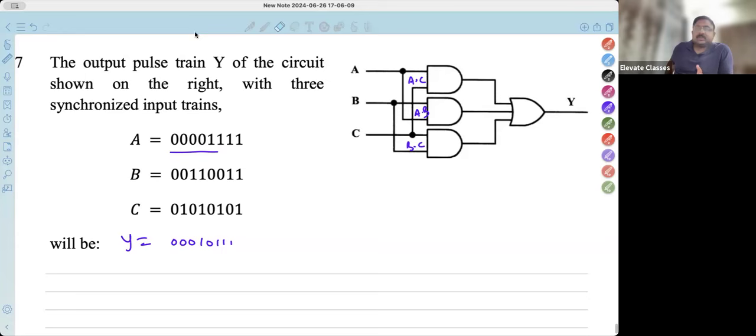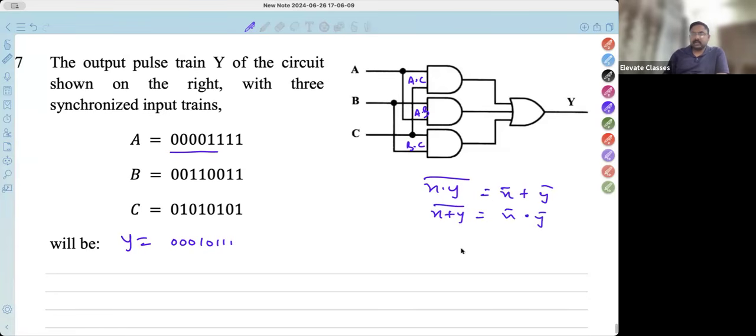De Morgan's laws. Remember, if there is a break, join it. If there is a join, break it. In complement operators, if you have x dot y complement, what is De Morgan's law? Dot changes to plus, and this complement operator is joined, so break it. Then you have x bar plus y bar. Again, plus changes to dot, and the joined complement is broken.